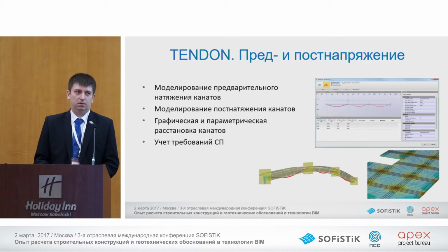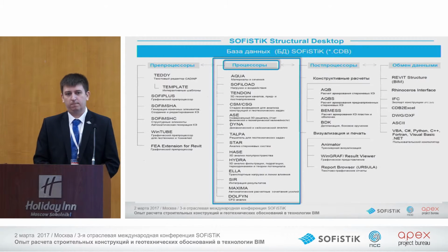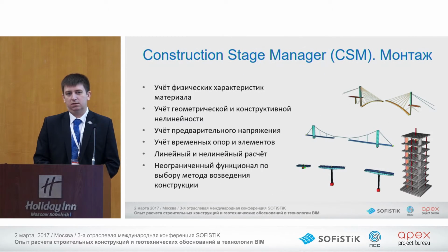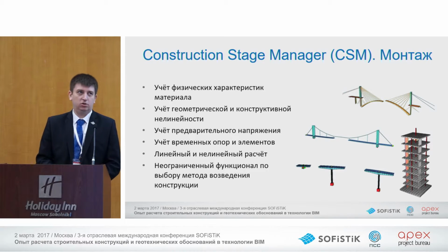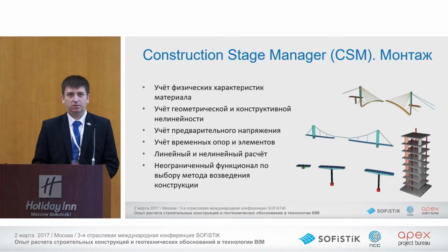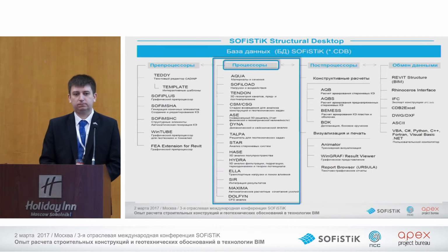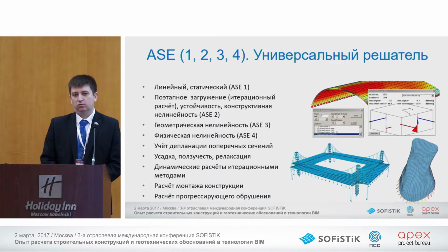You can create geometry and adjust pre-tension or post-tension. Construction Stage Manager, or CSM, is designed for construction sequencing, for bridges and for buildings and for different types of structures.